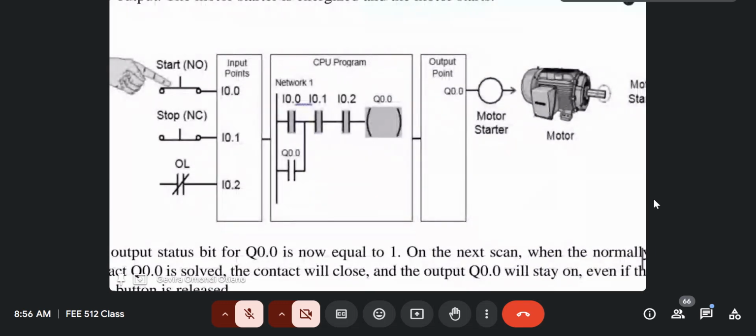It's very simple. Now somebody presses the start push button. You can see there's a hand pressing the start push button. When that start push button has been pressed, it makes contact. Now the contact exists. Once the contact is made, it means that the input module needs to change the state of the address so that that electrical signal would now be translated as a logic 1. Remember, it was a logic 0. It was a normally open contact. But now it is a logic 1 because now it's shaded, so the state here is now logic 1.